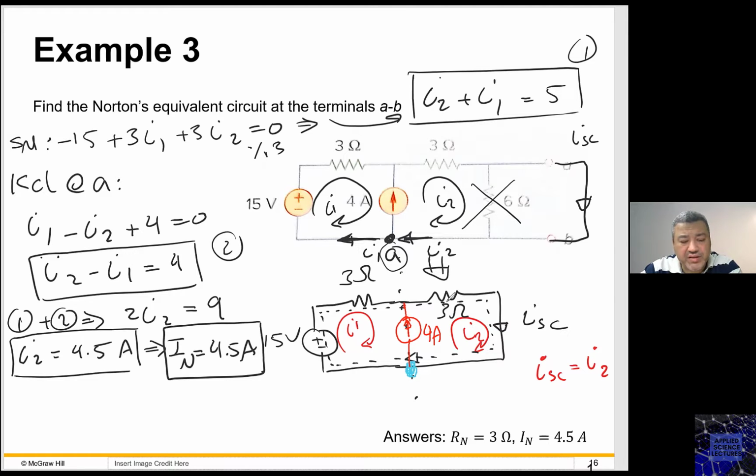It is a circuit that is represented by a current source. Sometimes you need an equivalent circuit made of a voltage source with a series resistor. Sometimes you want an equivalent circuit that is made of a current source. And in this case, the resistor would be in parallel with that source. Remember the source transformations we've seen.